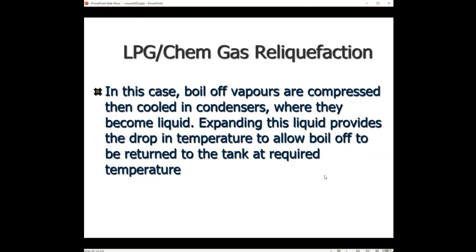But the ingress of heat is concentrated in the vapor. So by taking away the vapors of the tank, you take also away the heat. And that is sufficient. What you do then later on with these vapors is not so important. Whether you use these vapors for propulsion purposes or you reliquefy them, that doesn't matter so much.